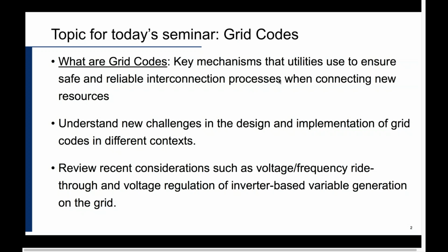In this webinar, we will talk about some of the most recent inclusions to the grid codes, such as ride-through, which means what should these new technologies do when there is an event on the system, and voltage regulation, which means what should these devices do when there is no issue on the system, for inverter-interfaced energy technologies.